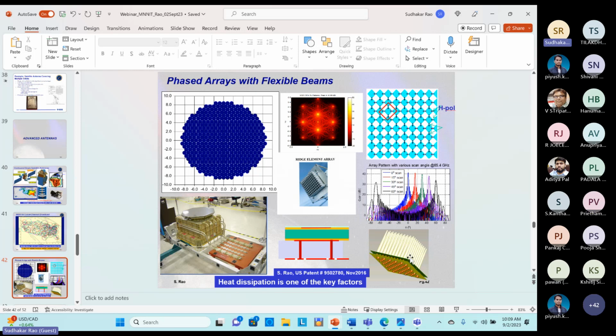So that's the reason 5G is even going into other bands like Ka bands, 26 to 28, 30, 32, and 38 to 41 or something. So there are bands allocated for future 5G. But right now, people tend to use low frequencies, while the future is mainly going to higher frequencies where you get the bandwidth. And even at low frequencies, people want to use a continuous band, a 900 megahertz band, right?